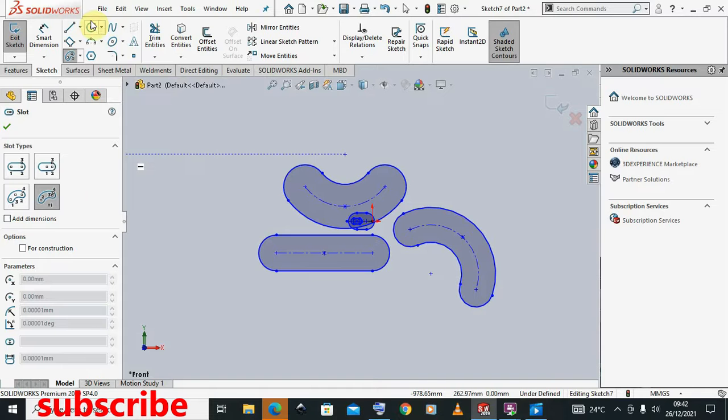Remember, the property manager gives more details about the command. Say 1, 2, 3, and always direct you with points. And if you're just a beginner, it won't harm you to follow the points over there. Say 1, 2, 3 as you're counting while looking here for whatever method that you're using. So for construction, if you set for construction, it means that whatever you're doing is not directly involved into the 3D. However, it's more of a reference to the general sketch that you want to do.